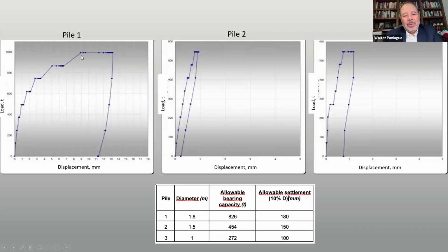And perhaps we can have some ultimate load in this graph, but not in this one, and certainly not in this one. So again, I think we should design basically on friction and have the end-bearing capacity as a reserve for certain things like construction failures, if you are in a seismic area, seismic loads or wind loads or any accidental load that you may have. But we are mainly wanting to design with friction because the displacement is so small and it's allowable for both